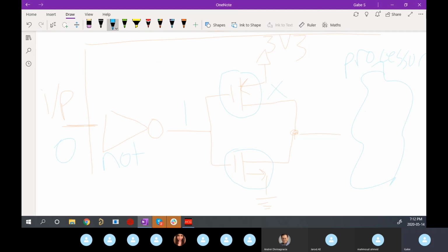My top gate will not close, and my bottom gate will close, right? And so this pin, which is connected to the processor, will read a 0 because with that 1, my bottom switch closed and connected that pin to 0 down to ground. And so that's how I read my processor. So if I had an input 0, my processor also reads a 0. So exactly what we want.